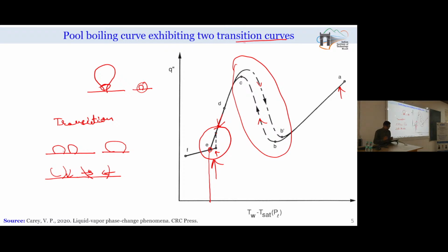Here you can observe that when two vapor volumes are forming and moving in the outward direction, our contact line is advancing. So, if we have an advancing contact line, the angle which will be applicable is the advancing contact angle theta A. On the other hand, when this vapor film is broken and liquid is re-wetting the surface, then this vapor volume is displaced in such a way that the contact line is moving towards the vapor side. It means this contact line is receding.